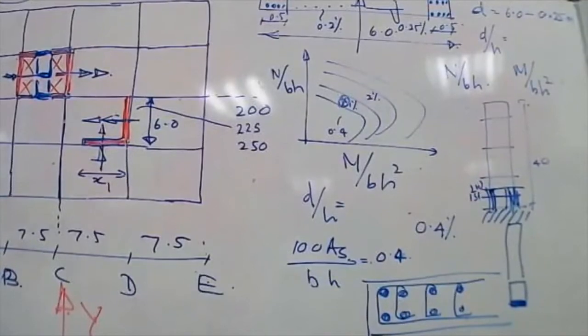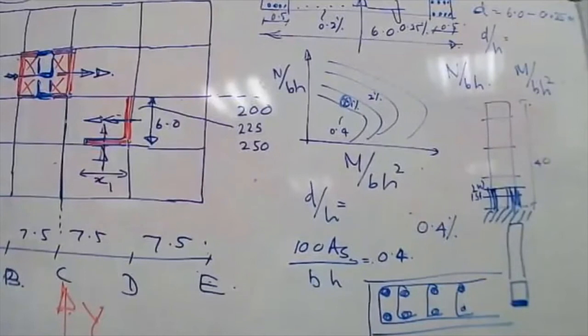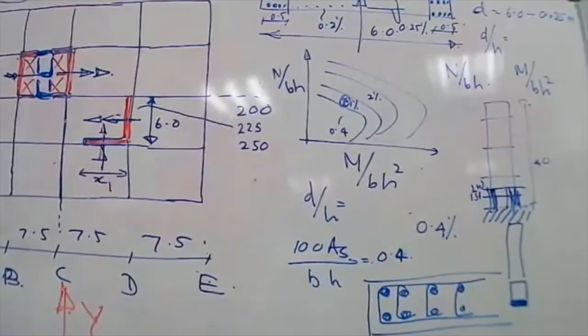So it's totally up to you, because when the column is behaving, it will go into a plastic behavior, not the elastic behavior. So in the plastic behavior, what matters is where the main reinforcement is. At the failure load, the wall will have a plastic behavior. So it's a cracked wall. What you need is a concentration of reinforcement at the ends. So it is purely arbitrary.